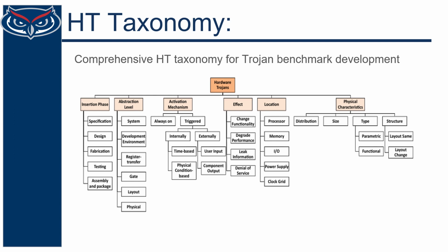On the other hand, at the physical level, all circuit components, their dimensions and locations are determined. A Trojan can be inserted in the white dead space of the circuit layout with the least impact on circuit characteristics.